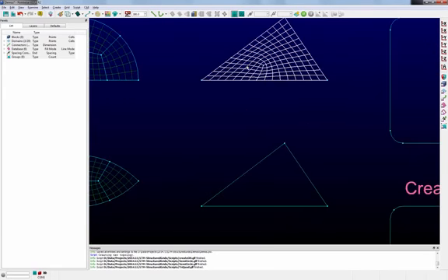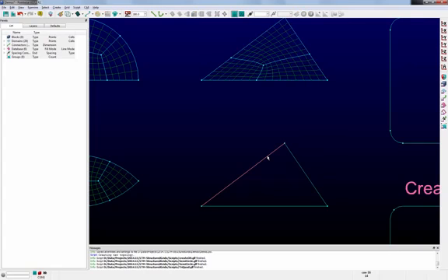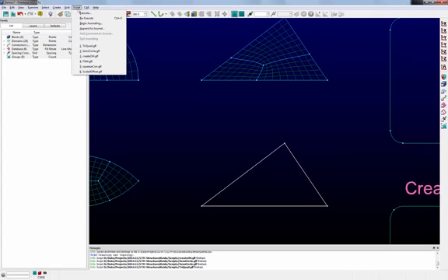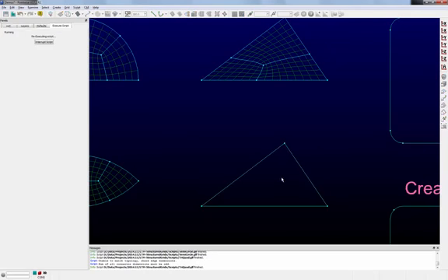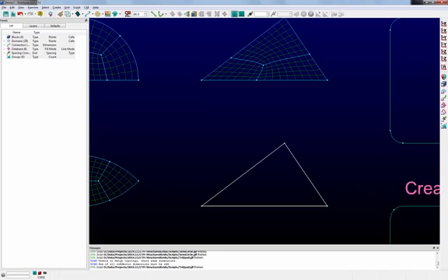Now, as I mentioned before, this is very sensitive to the dimension. So if you look down here, whenever I hover my mouse over this connector, it now has a dimension of 14. So it's not dimensionally consistent with that criteria I put forward earlier. If you try to run that same script on this set of connectors, you'll see down here in the message window that the sum of all connector dimensions must be odd. So it's not going to be able to generate that topology for you.